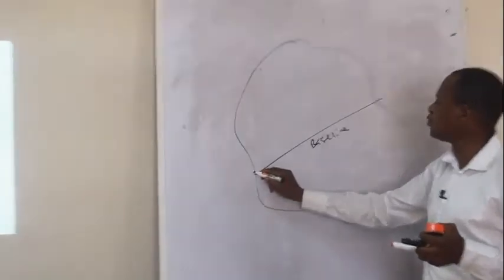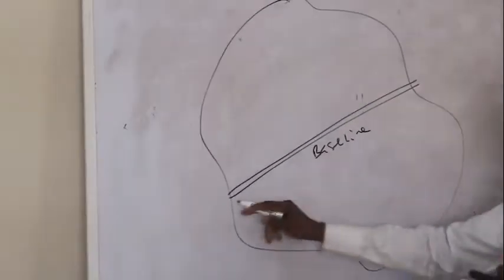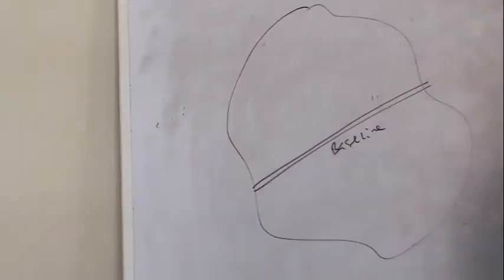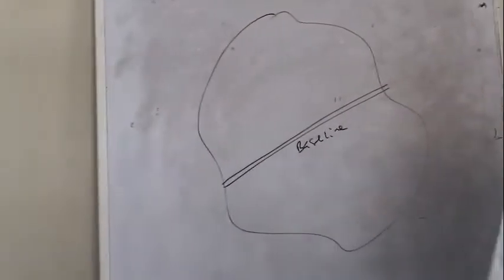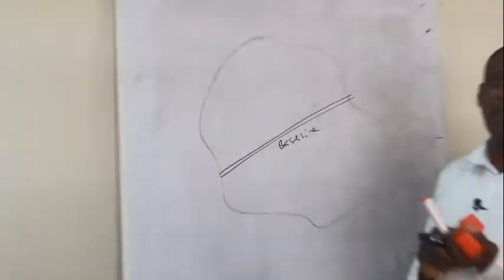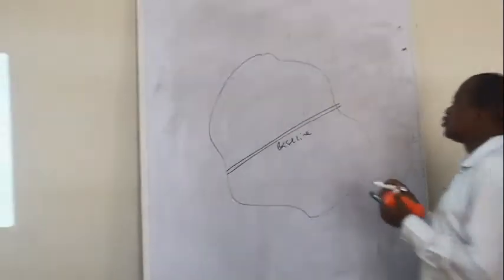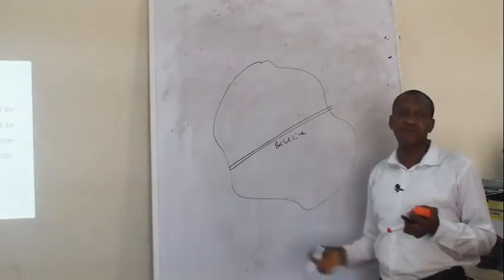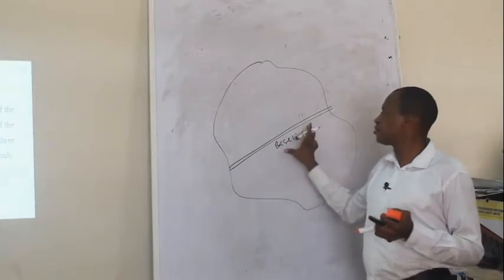No matter what, we normally write it and put a double line. That means we double chain. That is, we measure it twice, just as a matter of check to ensure that it is very, very accurate. Once that is done, on your baseline, you can begin to build a series of triangles.